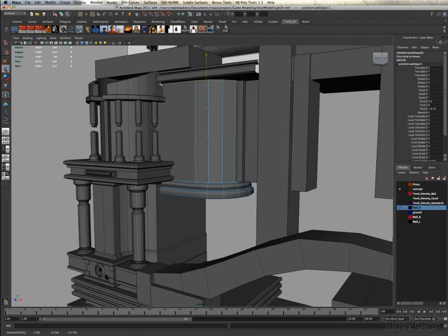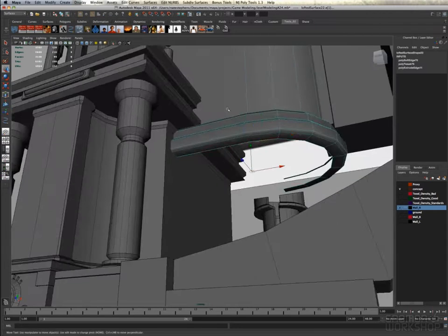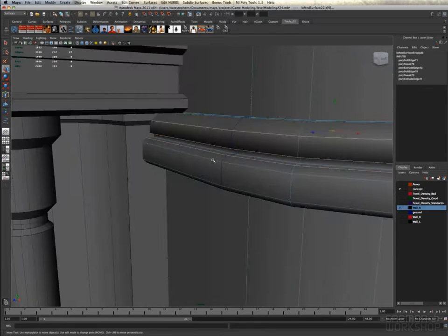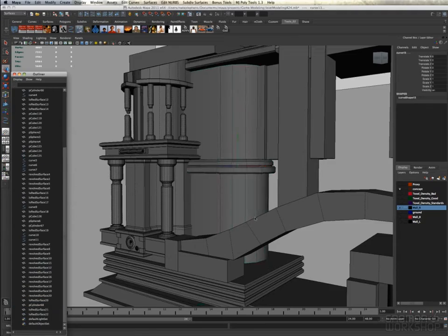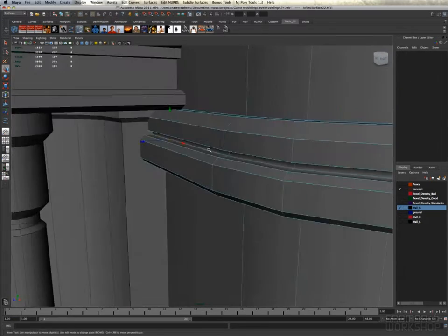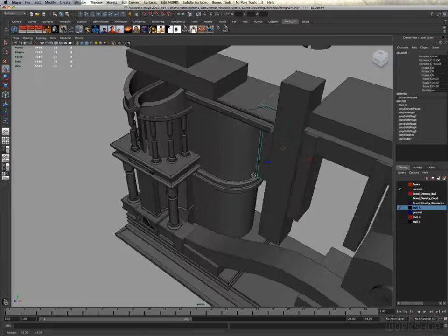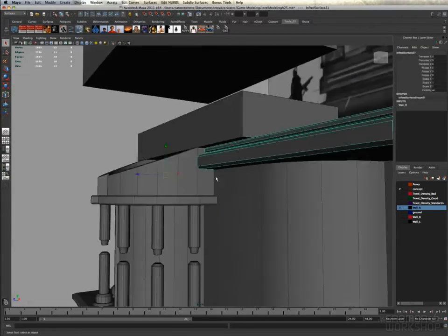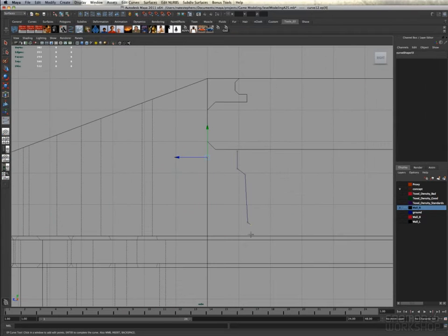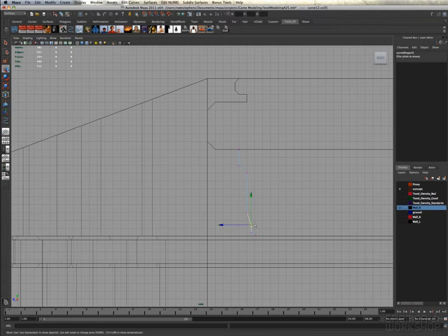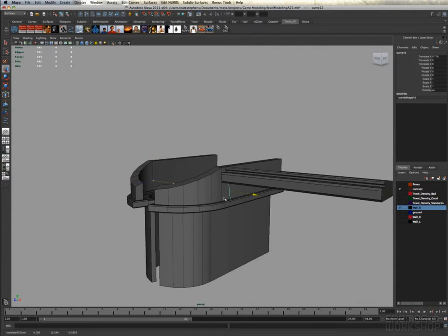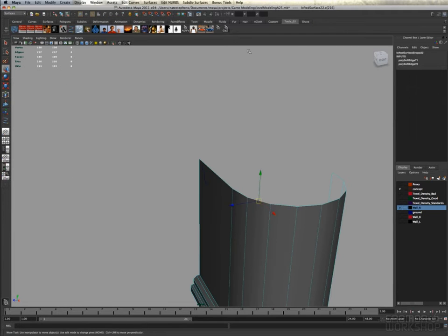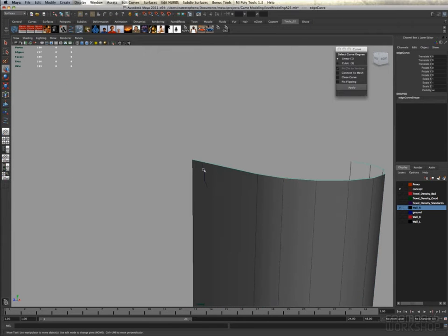You'll see sometimes after I revolve a piece or loft a piece, I'll have to go in and reverse the faces. And that happens because I probably drew the curve clockwise when it needed to have been drawn counterclockwise or something like that. Also, curves have a different direction, a start of the curve and an end of the curve. And based on how the orientation of the curves are, sometimes the faces need to be flipped. I don't really worry about getting it right as I draw the curve. I more just artistically want to figure out my shapes. It's easy enough to reverse them later.